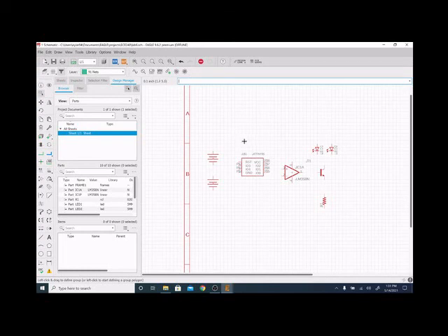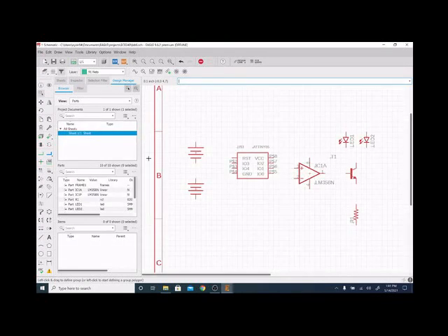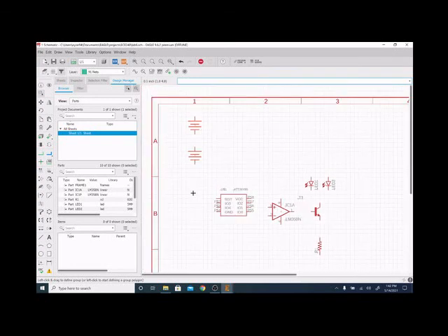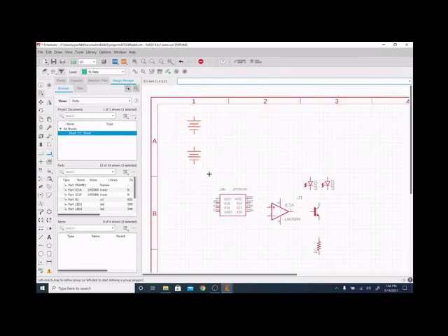And that's going to be done with the net tool. Alright, so all of our parts have been placed. I'm going to move these around just a little bit. So with my box select, I can select that little anchor point right there and drag those up. What that does is give me a little bit more space to work around. So I know that needs to be over there. That guy can move that way a little bit. Everything else seems to be all right.